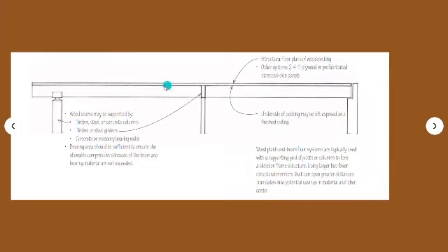So, just at the top, you can see the structural floor plan of wood decking. Here, the wood beams may be supported by timber, steel, or concrete columns, timber or steel girders, like here, concrete or masonry bearing walls. Bearing area should be sufficient to ensure the allowable compressive stresses of the beam and bearing material are not exceeded. So the wood plank and beam floor system are typically used with a supporting grid of posts or columns to form a skeleton frame structure.